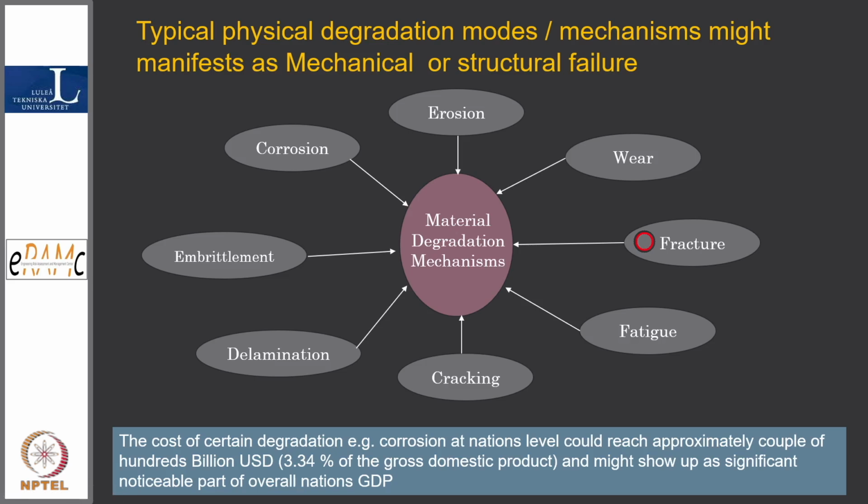If any crack is there, then you will be able to know through a sensor. But that also happens periodically. Let us say for each component it is a couple of years before its turn comes, and the coverage is always in question. So why not have an online system which can use secondary or tertiary leak-before-break kind of phenomena? Why allow fracture? Leak before break, even a small sweating should be able to tell you, and that can happen only with prognostics and health management logic.